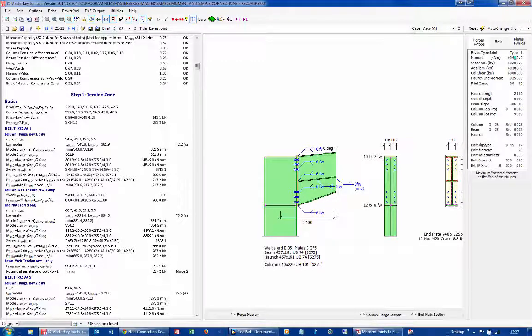The other difference between the two methods, the BS and the EuroCode, is the effective length. Previously in the BS, we took the distance from the bolt edge, spread out at 60 degrees, and we got a length of web in tension. Well, for some reason in the EuroCode, they say no. We now use an effective length that is the same as the effective length of the bolts in yield, LEF. So that's actually giving us higher capacities, even though we've actually had a reduction due to omega. So it's swings and roundabouts, but in the end we get a bigger capacity because of these omega and beta values.